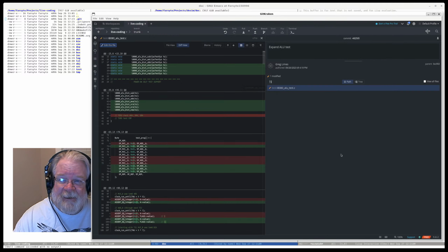And then I expanded the ALU test. So beyond the 4 tests we had, add, subtract, add with carry, sub with borrow, I added tests for and, XOR, or, and compare. And I did not go through and make sure that I tested each instruction with all of the possible flag results and all of that. I just blasted some values in. We'll do a more complete test later.